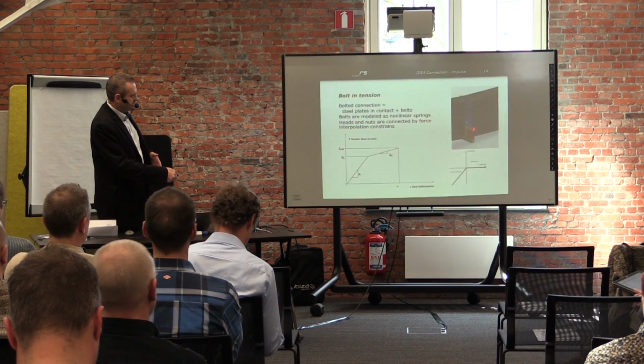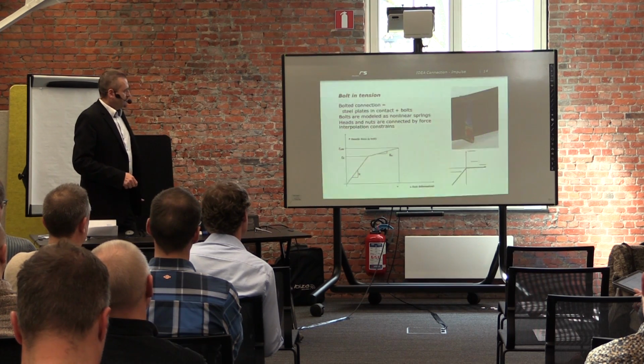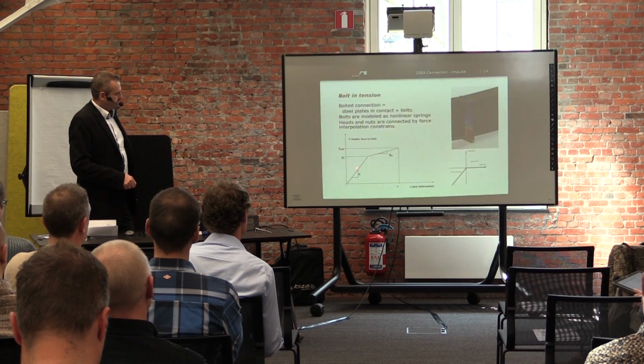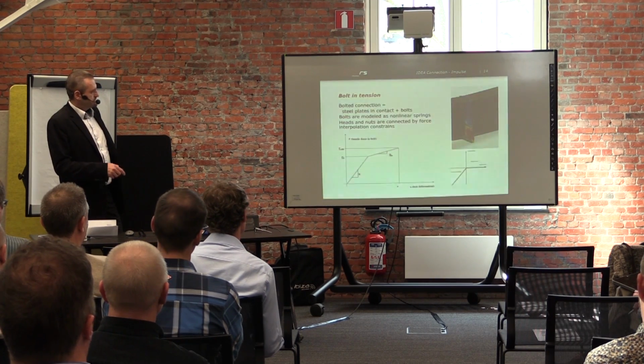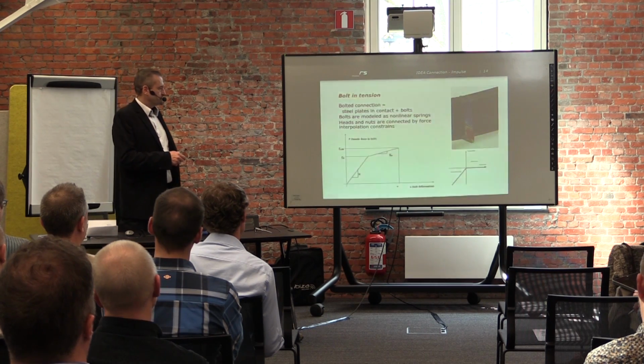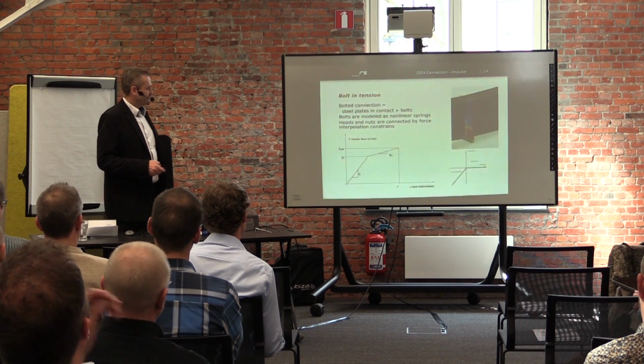So you see, like here, there is an opening between plates. And the bolts work only in tension, and we have to use a proper diagram which takes into account the plastification and other effects where the bolt is close to the limit force. So as Professor Wald showed in his presentation, this is the right model of bolts.